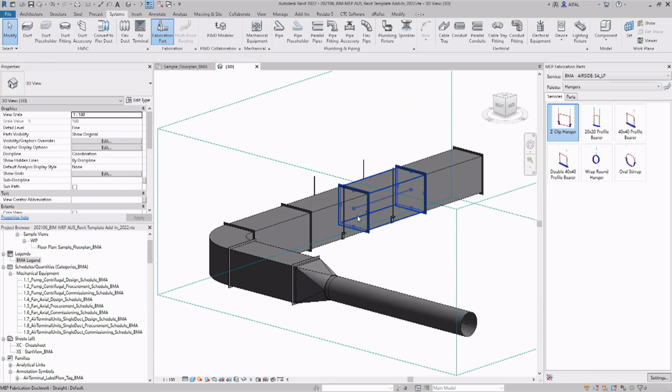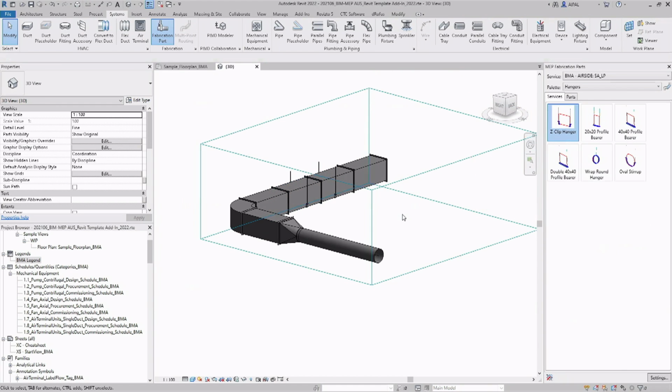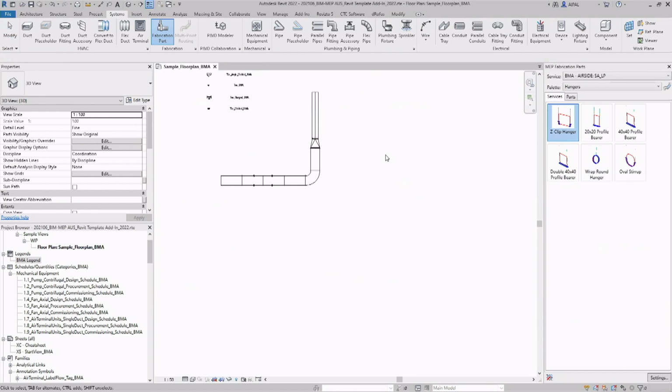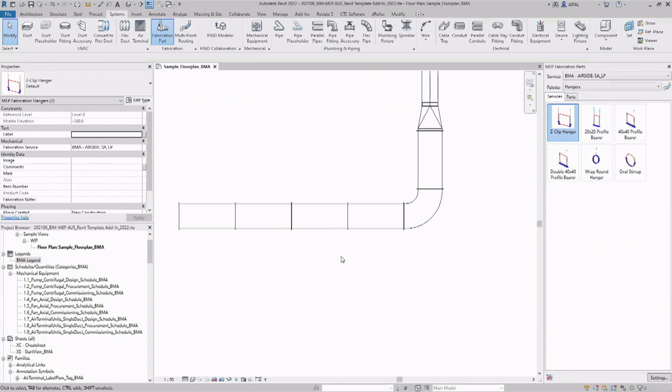And the good thing is also, if you have a BIM model where you have a slab above that duct run, the hangers would automatically snap to that slab, to that structural element. You would not need to track these hangers and increase the length or so. So that works pretty well here. Very nice. Something we can do here as well.